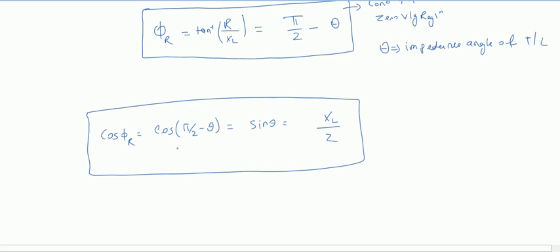These terms come up in objective questions. They will directly ask you for the expression, or if you remember the formula, it will be easier and faster to solve a problem. So this happens only in case of a leading load. Zero voltage regulation can happen only on a leading load. Okay.